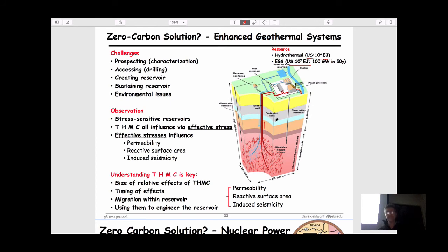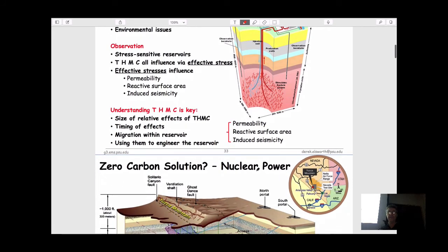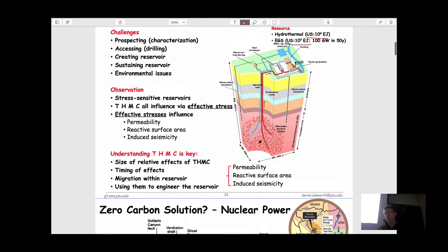You could reform them. So geothermal energy, push water in through a cold hole, flow it across a reservoir, tap it out on a warm hole. Once it's picked up the heat, take it to the surface, run it through turbines, generate electricity, make it cold, push it back down again, have a closed circuit solution. Lots of interesting problems, but basically it's an energy fluids problem, no different from the things that we'll talk about in this class. Pushing fluids through porous and fractured media, which they might react with, and from which they can take temperature out.